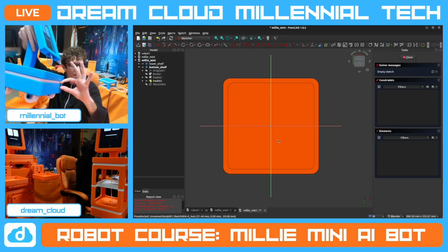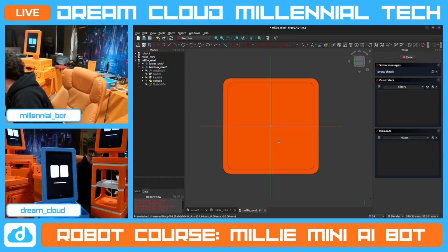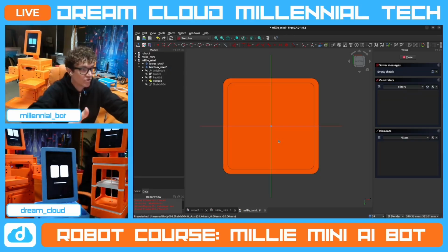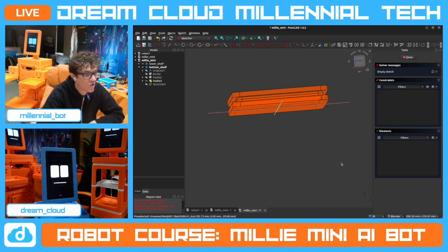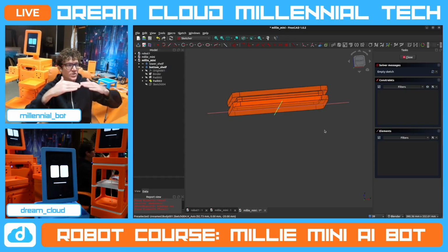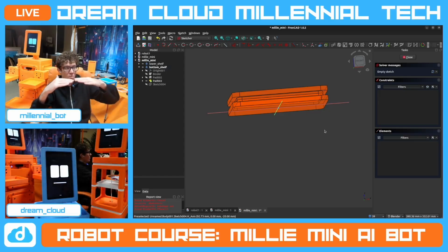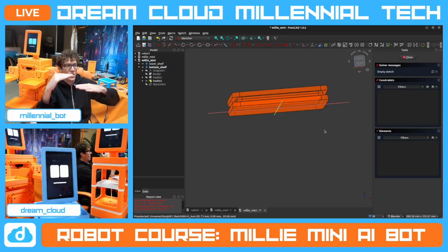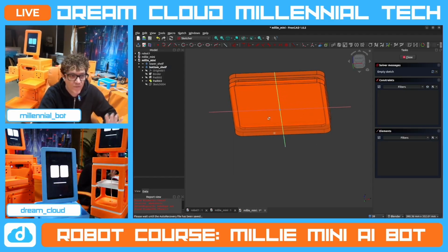We need to go from the pad we have now to the pad we want, but it's got to be hollow in the middle. So you can do that in two types of ways. You can extrude the whole thing. So what I could have done is I could have extruded this the whole distance, and then I could have turned around and created a pocket and shrunk it. But that requires you to change two different things, right? So if you wanted to change that distance, you would have to change where it's extruded and then where you pocket it again. So to avoid that confusion, we're just going to create the next shape.